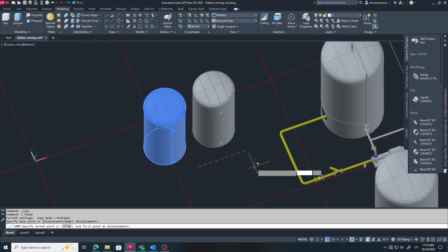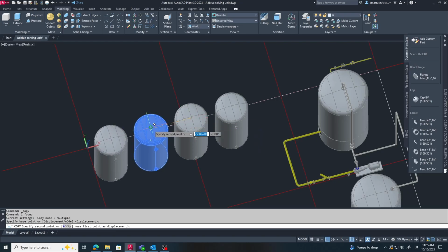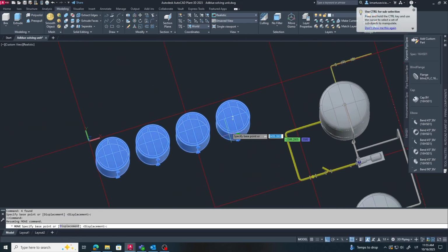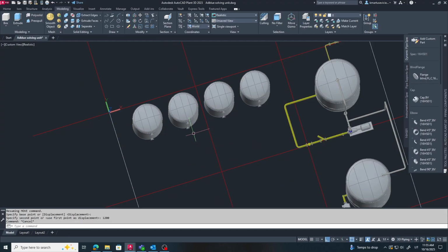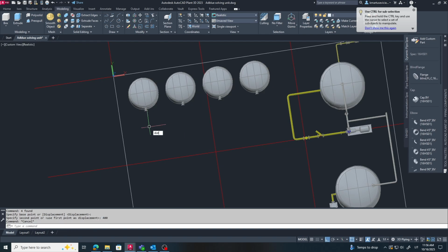Always think not only how to fit equipment in the model, but also how people will service it, open manholes, connect hoses, or inspect nozzles. These are small layout decisions that make a plant more realistic and maintainable in real life.